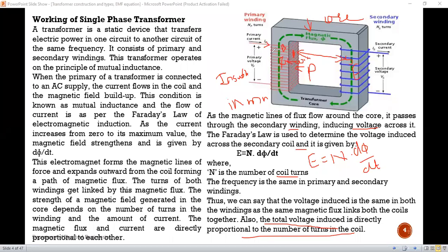The material used for making the core is nothing but high silicon steel, it will contain high silicon. Sometimes this material has high permeability, and the silicon is used to reduce the hysteresis loss. For the usual operating flux density, it will reduce the hysteresis loss. So to reduce hysteresis loss we use steel strip having high silicon content.